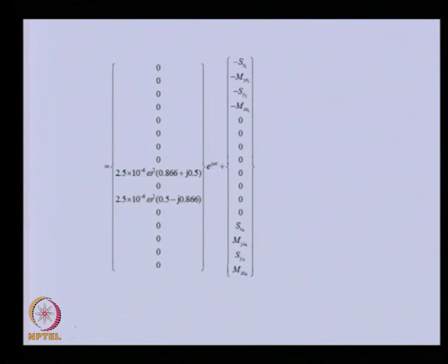Similarly, the reaction torque and reaction force will have this size. All intermediate reaction forces and moments will cancel. The unbalanced force is there at this node, the x component, horizontal component, and vertical component. There is no external force in any other nodes. Only at 2 locations, corresponding to the horizontal and vertical directions, are there forces.